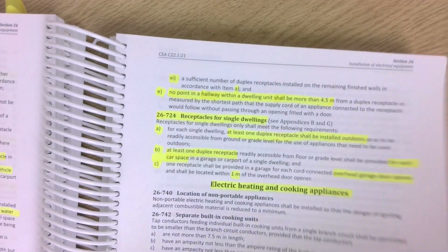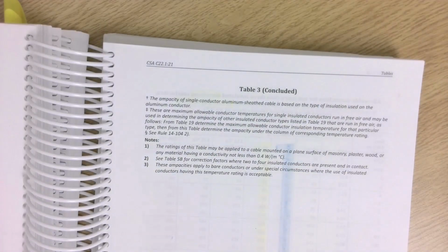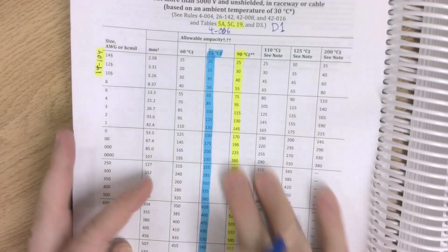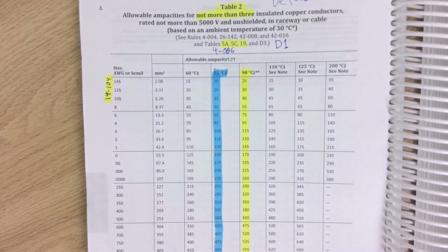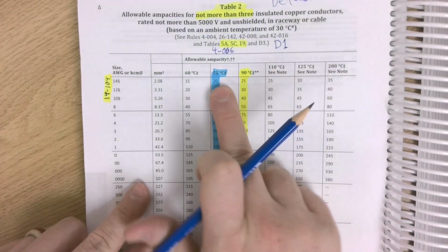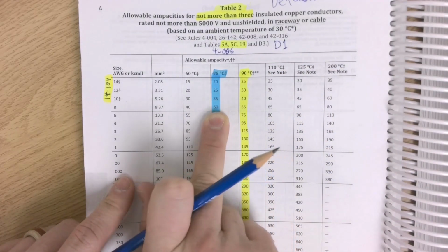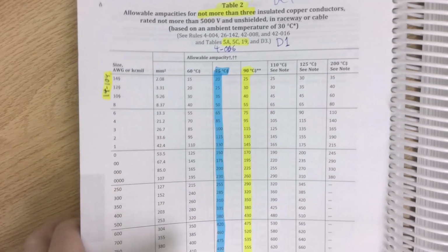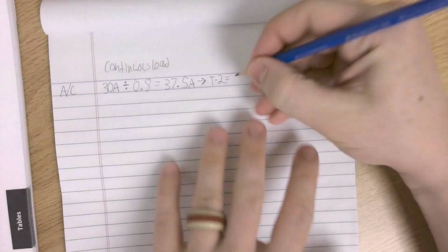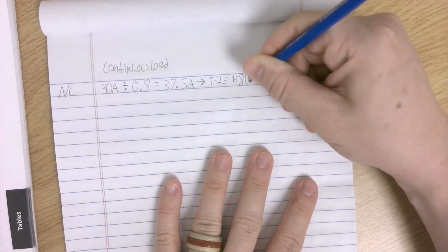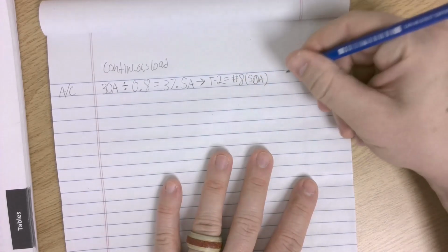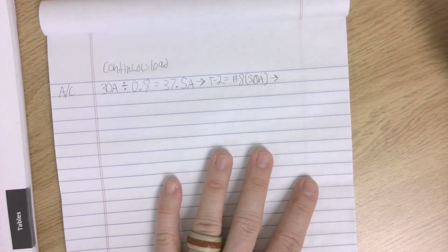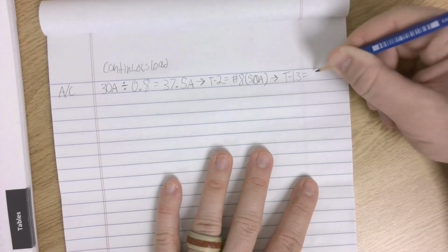So let's jump to Table 2. In the 75-degree column, and we'll say for this purpose that the air conditioner is fed by a 3-wire cable, there's nothing funny going on in that regard, we're going to find 37.5. Nope, it needs to be a number 8. And I remember 14-104, so I know that number 10 wouldn't work anyway. But I'm repeating myself now. A number 8, good for 50 amps. And I know from the range question that there is a 50 amp overcurrent, so I'm going to say Table 13 equals 50 amp overcurrent.